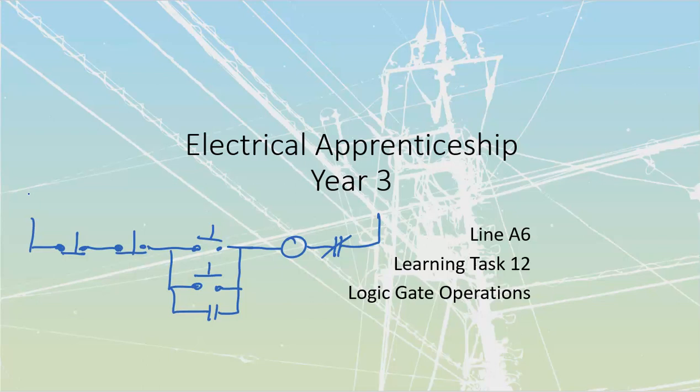We've got two stops that are in series. We have two starts that are in parallel. We've got a seal in contact and a set of normally closed. If you do not understand this drawing at this point, you've got to go back. You've got to make sure that you're prepared for motor controls this year, because this is baby stuff, all right? We are going to go far more in depth than this, but this is the one that we're going to work with today.